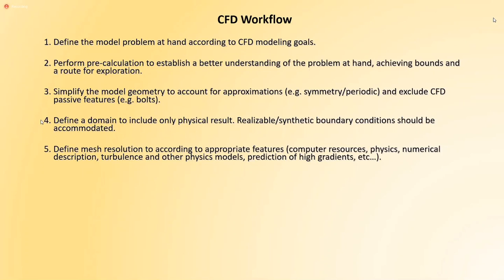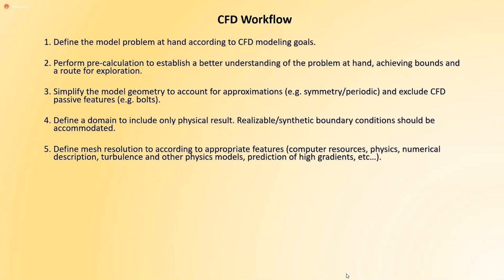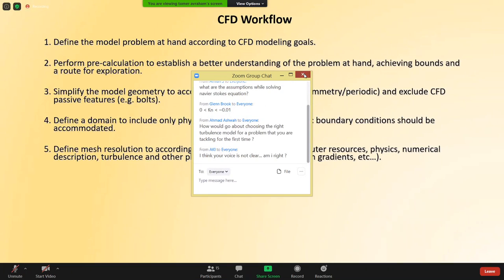But very important, the numerical domain. If it's aeroacoustics you're doing, you can't have reflections from the walls. If you're solving a problem of an atmospheric boundary layer, you need the atmospheric boundary layer to become an atmospheric boundary layer before it gets to your building. And so you need to take this into account. This means that the domain is usually larger than you want it to be.